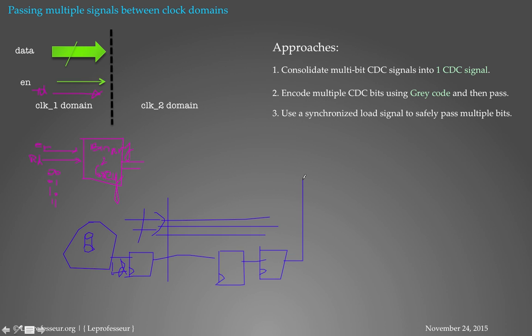However, it's always good practice to send a feedback signal back to the sending clock domain, which makes sure that your data is being properly read.